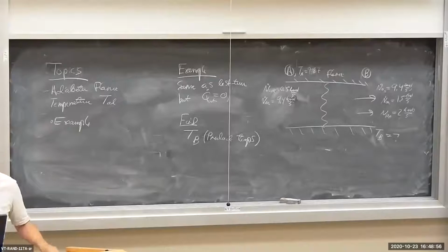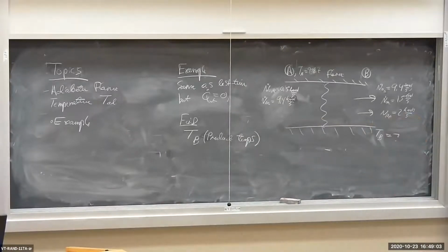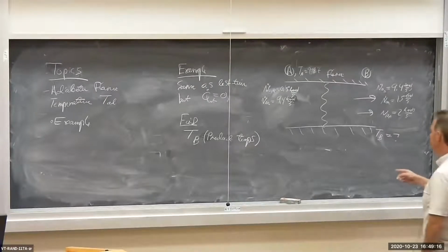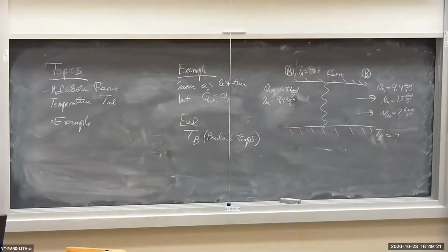All right, ladies and gentlemen, let's continue on with combustion, reacting systems. Last time we calculated the heat rejection by burning propane stoichiometrically in a combustor. That problem was relatively easy to do because we knew the exit temperature. We knew the product temperature, TB, in that case was 500 degrees Kelvin. So we could immediately calculate the specific enthalpies for all components at the outlet as well as the inlet. So that was a relatively easy problem to do. Let's do a slightly harder problem today.